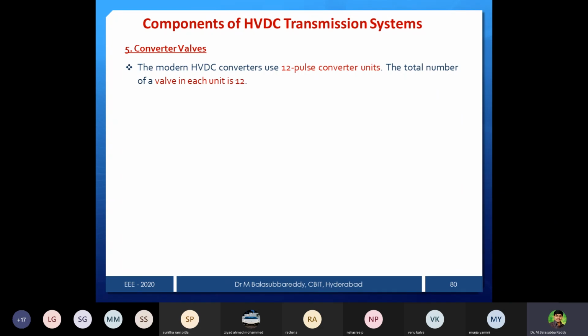But I will show you using the graph how, if alpha or overlap changes, what the values are, because we need to design the valve. For so and so degrees, between this degree and that degree, what is the output voltage, what is the valve 1 voltage, valve 3 voltage, and what is the pole voltage.